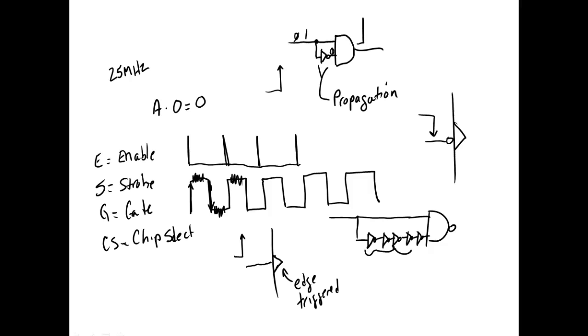The edge detect circuit itself is not complicated. We see a lot of counters and stuff like that count on what? On edges. They don't count on levels, they count on edges. So just about all our counters are going to be edge triggered for obvious reasons, right? Because if I'm going to count, I don't want that thing counting up on the high level. I just want it to count every time I see an edge come through. So we'll see when we finally get to the counter. So those are edge triggered circuits. Level triggered and edge triggered. Y'all understand the terms?